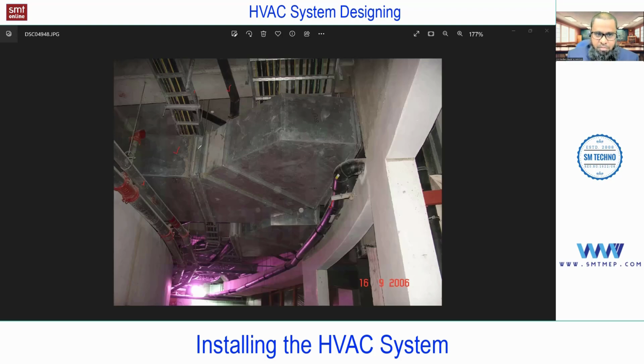Okay, so you see, first of all, this cable tray is above the duct, so that if any condensation happens on the duct, it will not lead to a short circuit. This is from a safety point of view. This is a standard practice, but in actual practice, you may find the cable tray running below the duct.